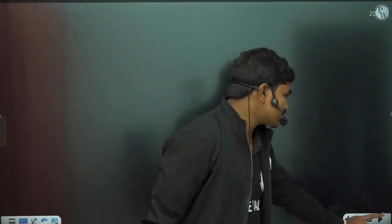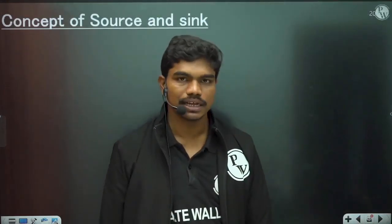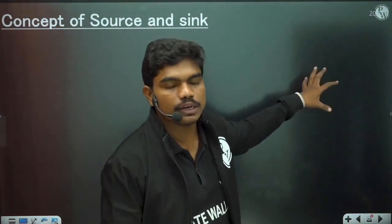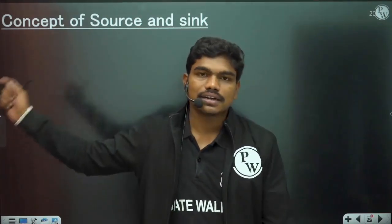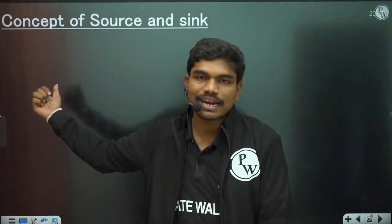First of all, let us discuss the concepts of source and sink. Then afterwards, when I derive the doublet, that n equal to -1 situation is called a doublet. When I explain what a doublet is and what its complex potential function is, you will understand that the complex potential function, basically f of z for a doublet, is the same as the case when n equals -1.